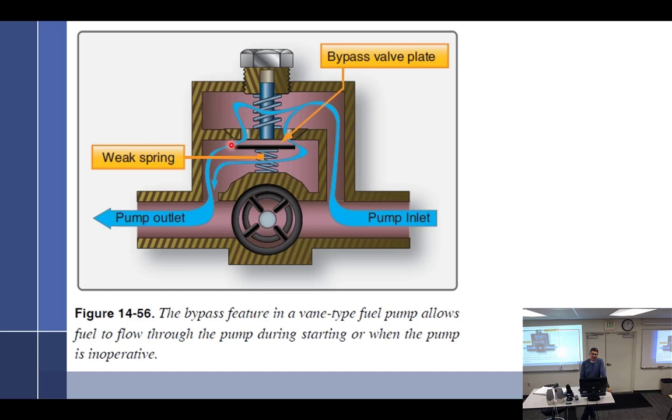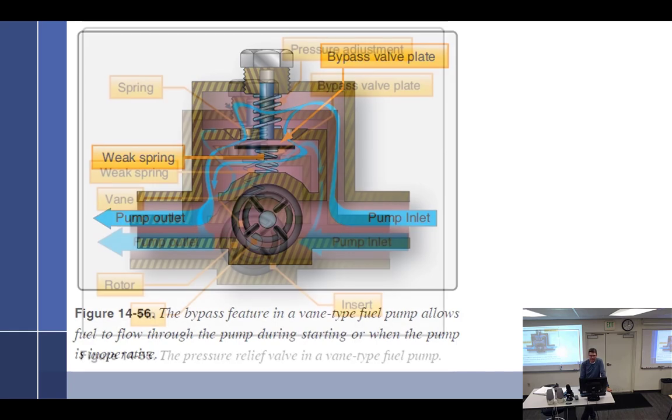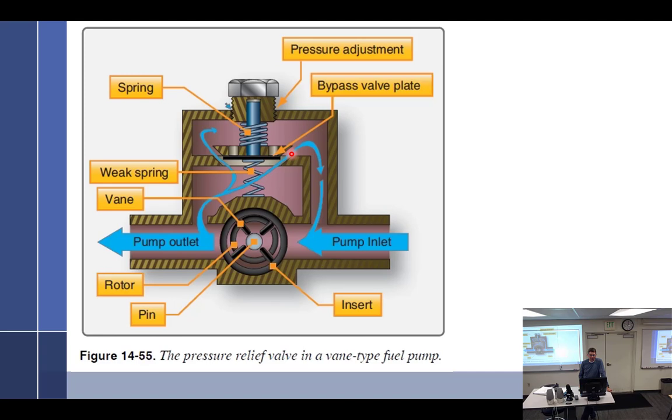So the bypass does two things. What are the two things? One, fuel through when it's broken, and two, fuel through to start. Okay. Then once it starts, boom, fuel's going to come through here, go through the pump and go out this way, out the pump.